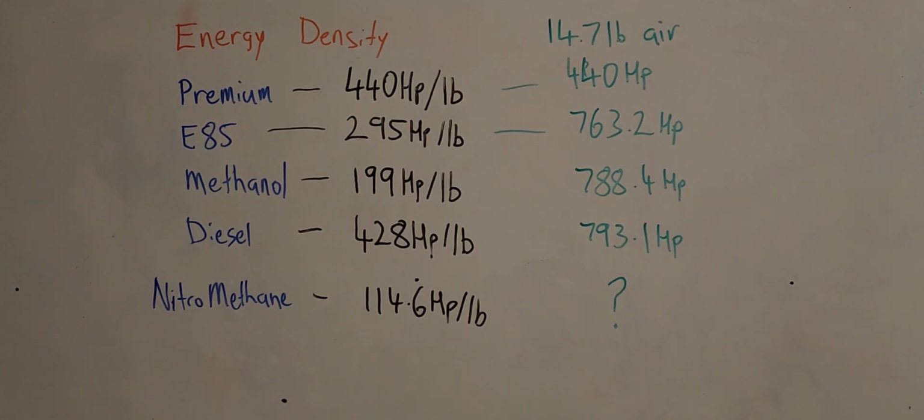Why? Because the energy in the fuel and how much we are now putting into the engine has gone up. So we could lose thermal efficiency yet still gain a final horsepower number because of the amount of energy that is in the fuel that we're chucking at it.